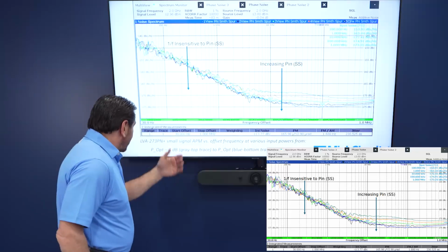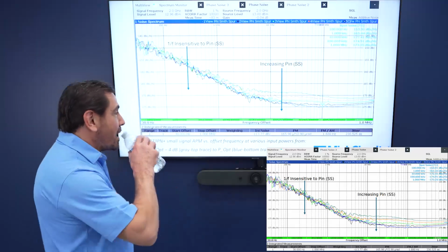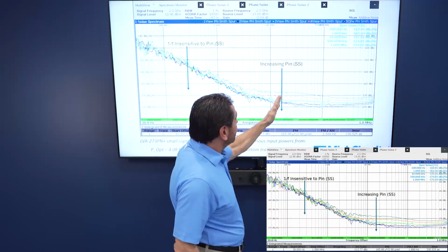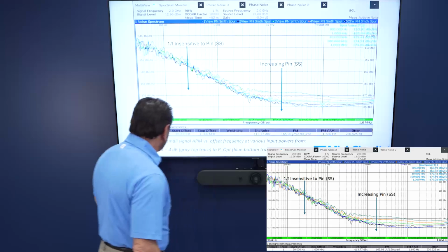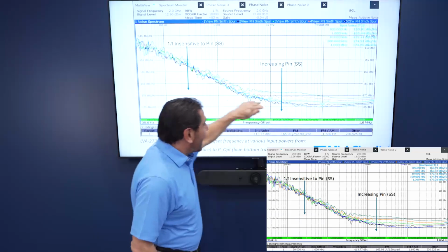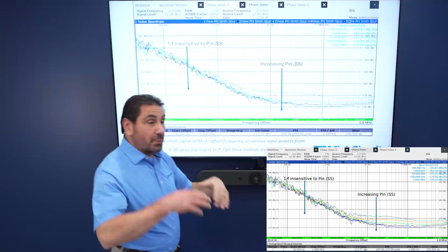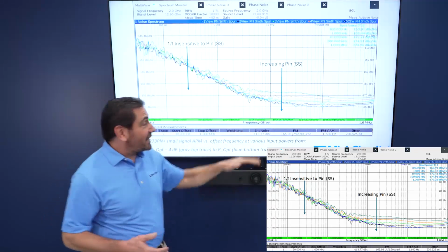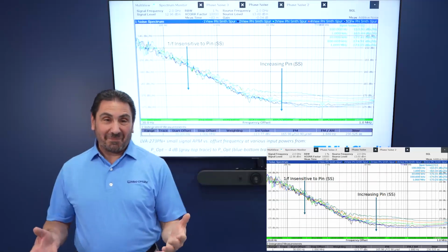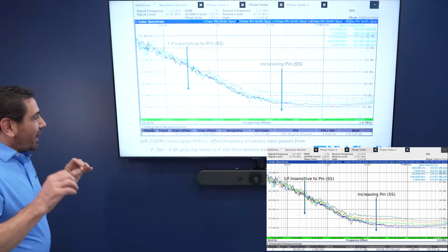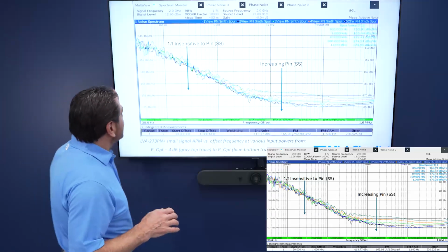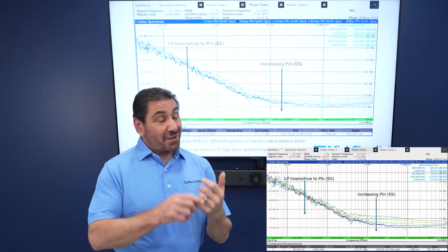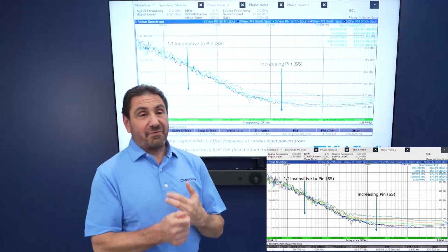So again, here's our favorite LVA 273 again. And we're showing the effect of increasing the input power. See here, we go to this bottom we're calling the optimum, and this is 4 dB less. And as we increase the power, just like the graph said, the white noise power looks like it's improving. It's really the signal noise ratio. Very interesting, I don't know that I mentioned this, but look at the 1/F. It doesn't really change as a function of power. It doesn't really change as much as a function of power or carrier frequency.